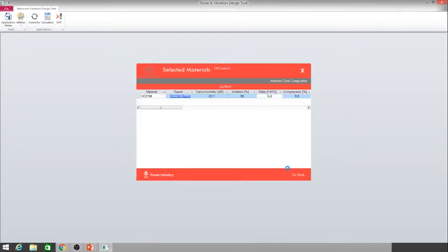If we continue, the output will be the material selected. In this case it is VC2100, and this one is easier because it's the only one that can be used inside the transformer. We can see the value of transmissibility, the percentage of the insulation, the ratio between disturbing frequency and natural frequency, and the compression on the pad, 9%.